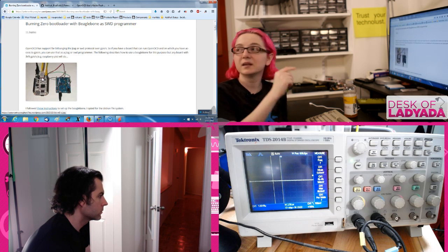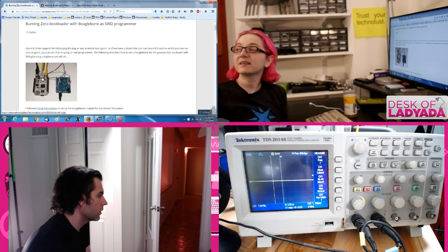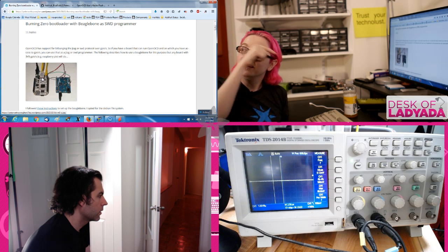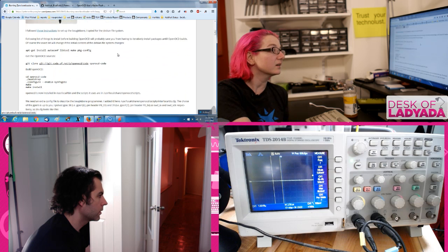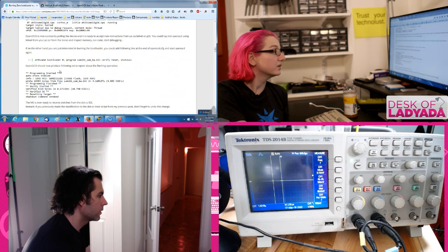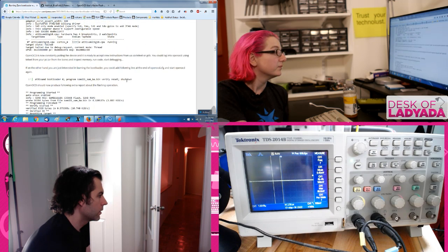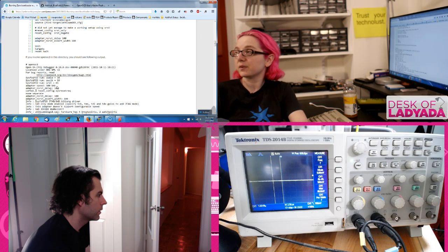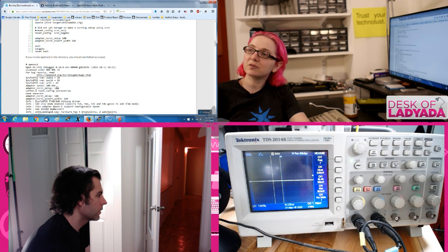Yeah, this is the M0, the Arduino.org one that doesn't have the debugger built in, and so if you want to burn the .cc bootloader onto it, so it works with the .cc IDE, you have to go through stuff like this. And he's like, it's a pain, but he got this working. And yeah, he figured out this command set. You can also see it from within the Arduino GitHub repository. But I saw this and I was like, that's interesting. I didn't know you could use native pins, but that got me thinking, I can have a Raspberry Pi and it would be.